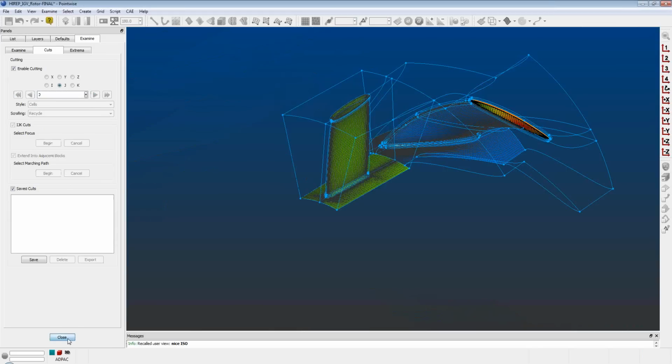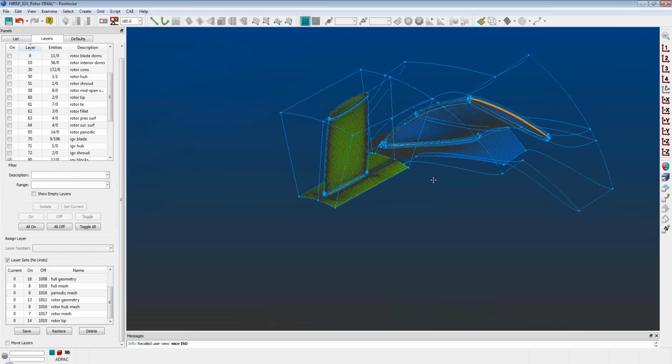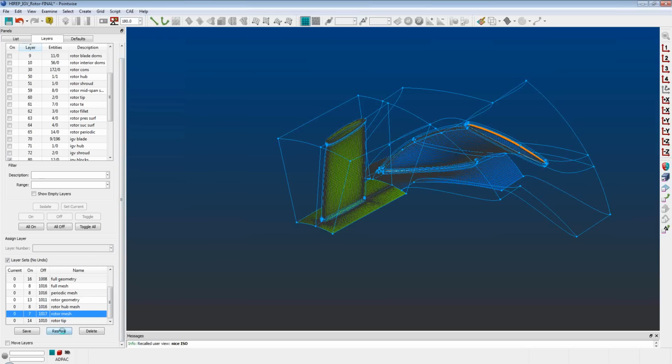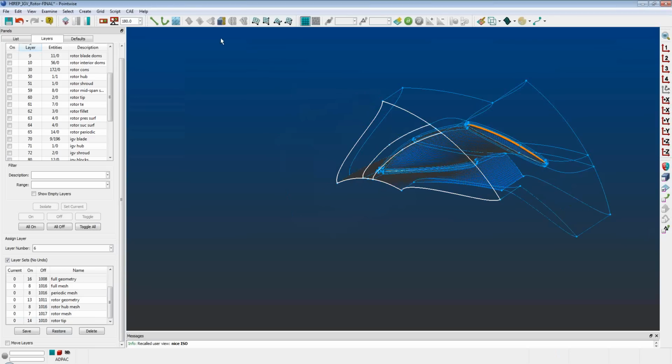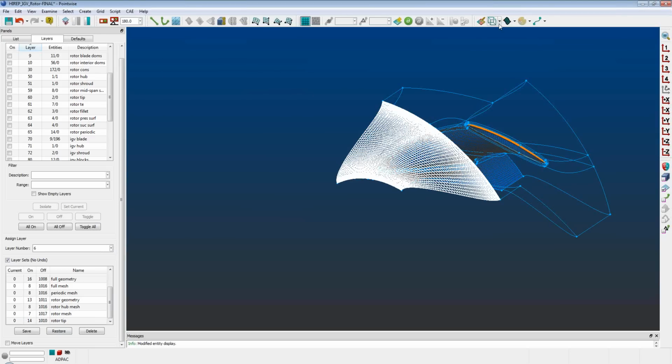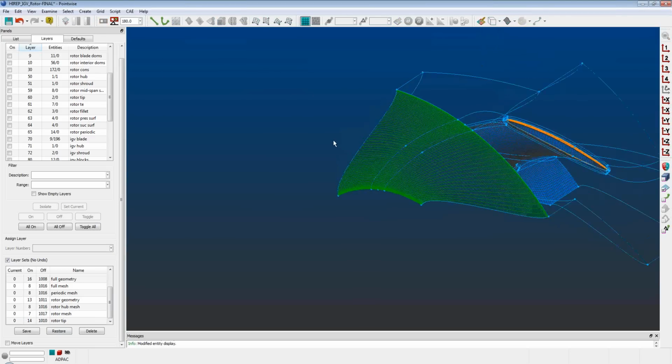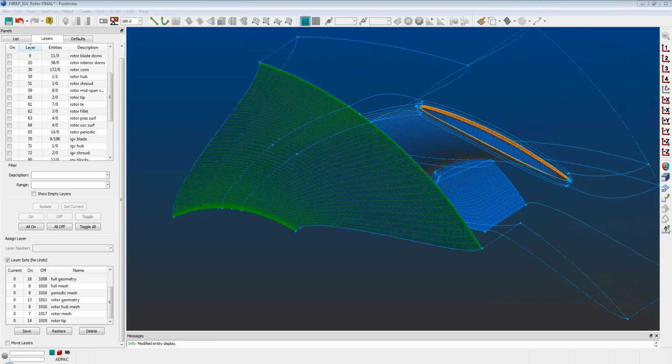we typically, in our usage, don't do this simply because we find that you can sketch out a reasonable shape in a very quick time, and by keeping the topology relatively simply shaped, we find that it just makes it easier to go in and edit it and understand the grid topology when you want to change the grid dimension or something like that. But there's absolutely no reason you couldn't run the solver in the blade-to-blade plane and float the periodic edges to get a more organic shape there that would maybe reduce some skewing.